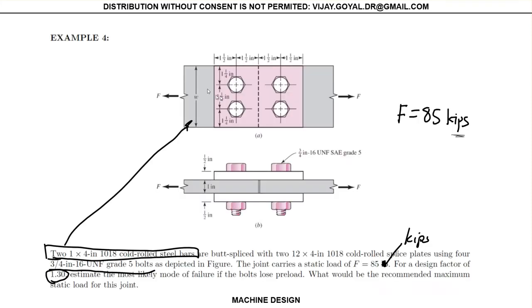Okay. The second thing we want to check is bending. To check bending, you can see that the maximum distance I have in the problem is 1.75. This is in the midplane of the plate. 1.75 is roughly here in this direction.